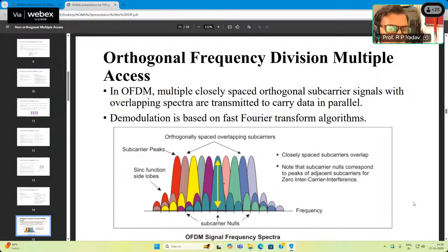And another advantage, if you have studied a little bit about wireless communication, is that channel fading can be negotiated, particularly frequency selective fading. The advantage of OFDM is that it converts this frequency selective fading into flat fading. That means no signal of any frequency gets eliminated or disappears. Rather, that signal can be retrieved easily, even if this kind of fading comes across the signal transmission.